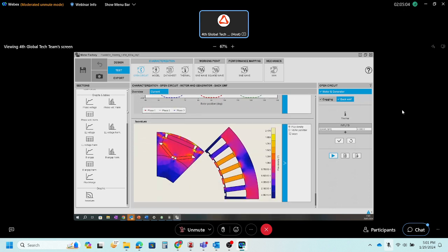To conclude, we have the iso values of the machine, where we can find out if we have saturation in some parts. This can be seen because we have a very thin web, so it is quite expected that some parts of the machine can be saturated like this.